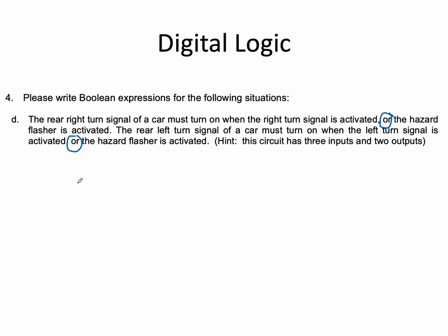And so you can actually do a 3-input one. So here's the right-hand turn signal. That's supposed to be an input over here, just a dot. You've got the hazard over here. I'm going to label that as an H. And I'll put the left down here. And I'm actually going to draw this as a circuit, not as a Boolean expression, just because it makes it easier. And I'm just going to use some OR gates. One OR gate here and one OR gate here.